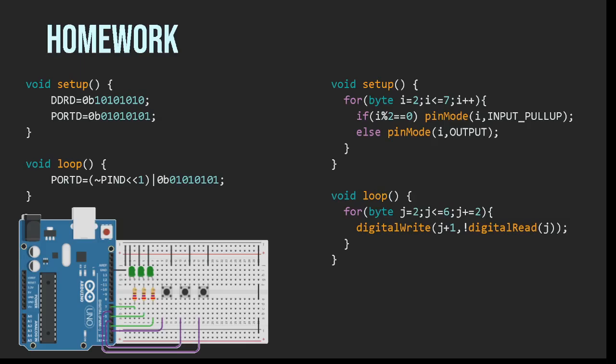The reason for this is because I declare my buttons with pull-ups. That means that if I don't press the button, I will be reading a logic 1, right? So if I am not pressing and I don't have the NOT, I will have the LED turn on. And I want it to turn on when I press it. That's the reason I negate that press. So when the button is not pressed, I negate, the LED is off. When I press it, it reads 0, I negate it, it's 1, so the LED should turn on, right?